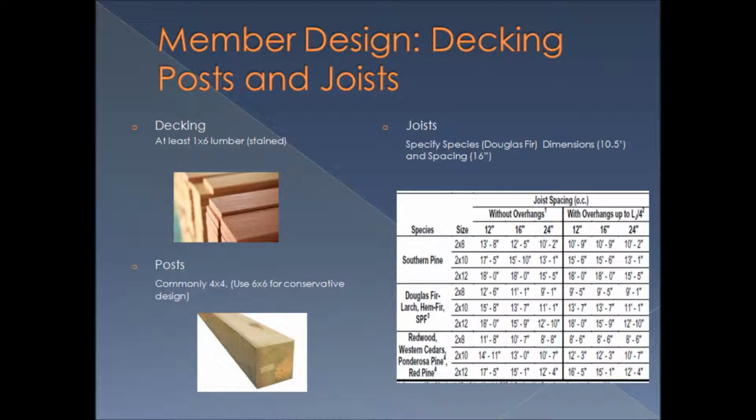Taking the load from the decking surface are the joists. These joists are typically 2x pieces of lumber, and based off the dimensions of the deck and what part of the country you live in, can span up to 18 feet maximum.